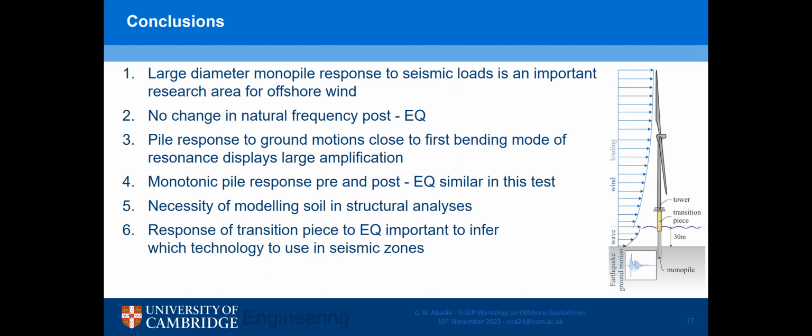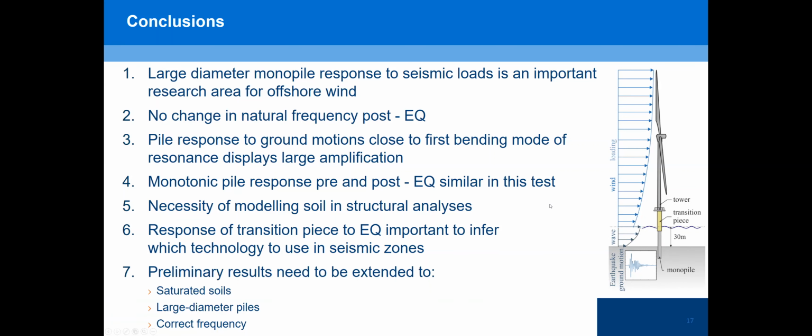The response of the transition piece to earthquake is also important to infer which technology we're going to prefer in seismic zones, be it grouted or bolted. Both of them have major problems, until transition-piece-less technology is ready, which is currently being investigated. Those results need to be extended.